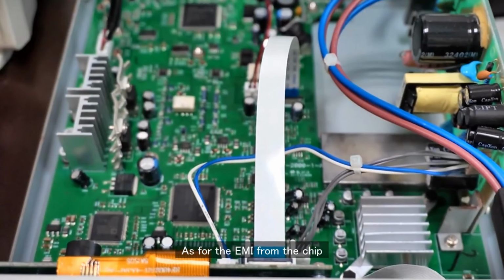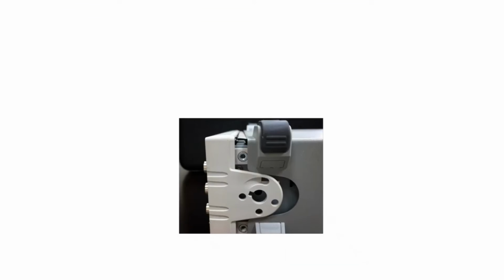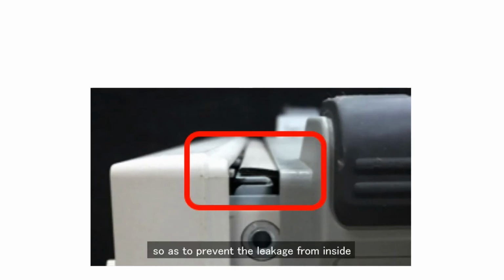As for the EMI from the chip, a series resistor or shunt capacitor can be used to reduce the EMI of the clock signals and their harmonics. As for the gap between metal materials, you can fill it with EMI gasket so as to prevent the EMI leakage from inside.